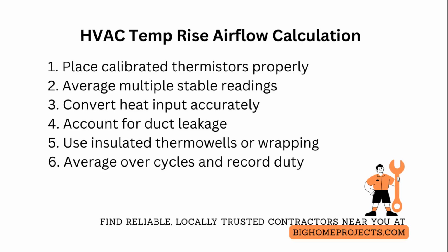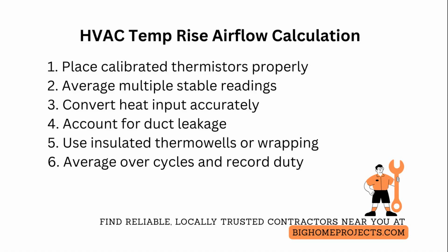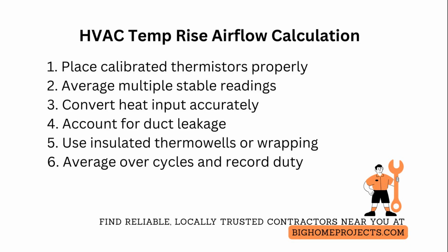Document all sensor locations, calibration offsets, and measurement uncertainty so your computed cubic feet per minute has a stated confidence interval. This is critical when handing results to building owners or for code compliance.